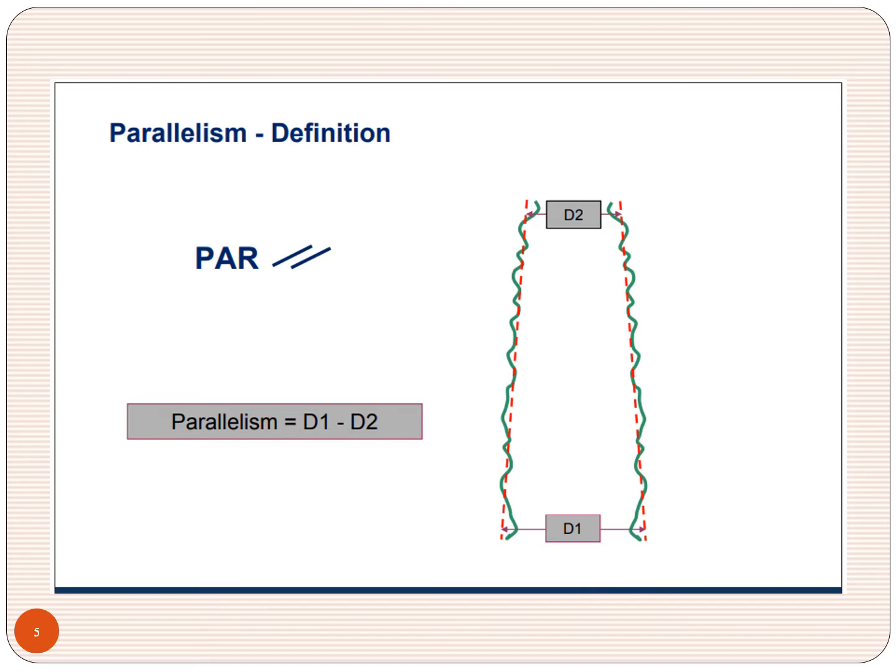Look at the formula for finding the parallelism: D1 minus D2, maximum minus minimum, that gives the parallelism error. That is, parallelism is not perfect. It may be 0.001, that is 1 micron, but that is negligible if it is within the tolerance limit. Even for a cylindrical rod, we are measuring the parallelism and the straightness. Why don't we measure for gears? That is the question that arises.